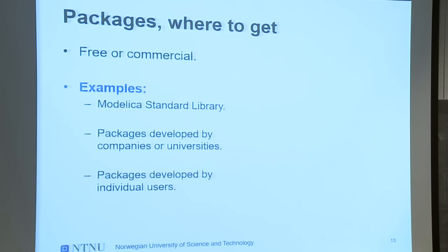However, if you want it to be really nicely interchangeable, you still have to define things like connectors the same way over all packages. Otherwise, you can get problems connecting different packages. Do you use Modelica and Dymola also for steady state simulation? You can, but I'll come to that.